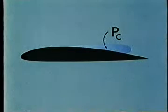Operation with a cavitation number well below the critical produces a very large cavitated region. In two-phase, one-component flow, the cavity pressure is just the vapor pressure. In a multi-component flow, the cavity pressure is the sum of the partial pressures of the vapor of the liquid and of any gases that may have been introduced into the cavity. In fact, a cavity developed entirely with gas from an outside source behaves and appears very much like a cavity formed by means of the vaporization process we have been discussing.